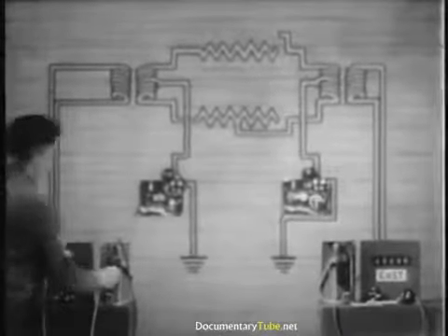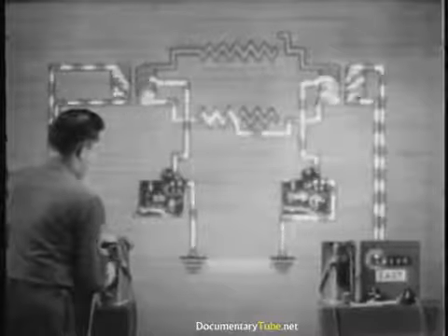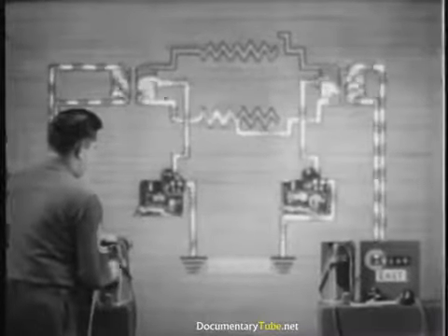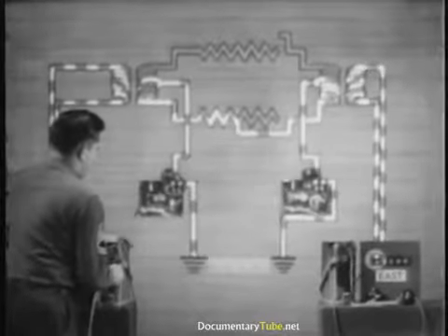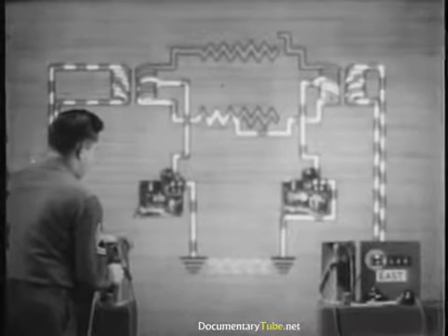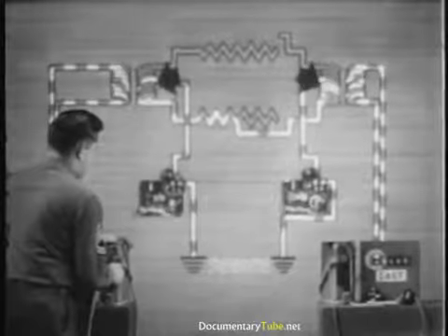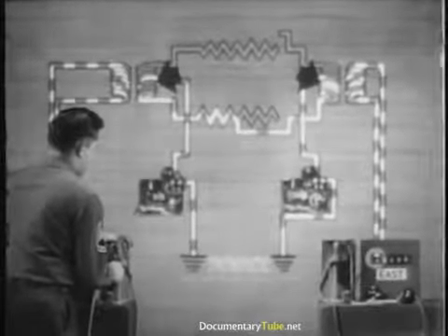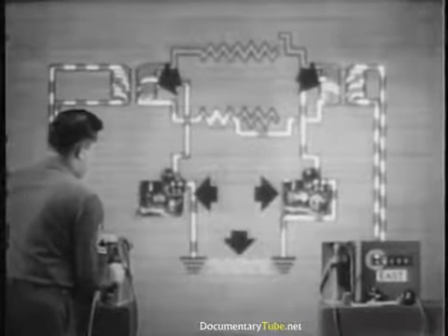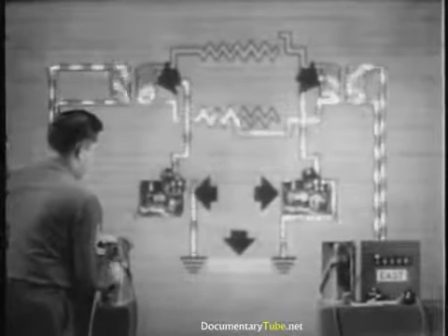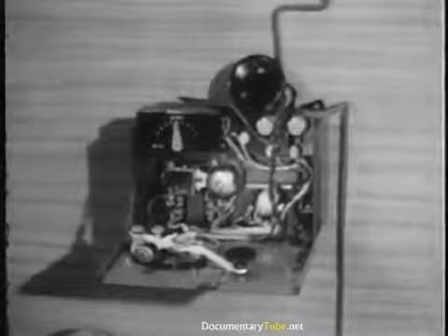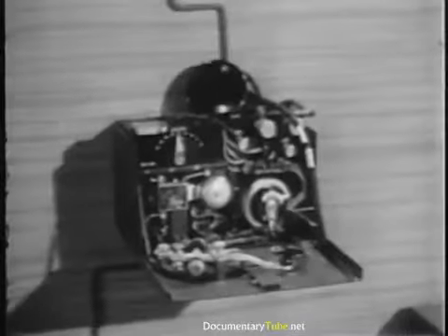Telephone signaling is usually still possible, even with the open line wire. The low-frequency ringing current uses the available half winding of each repeating coil, the telegraph sets, and the earth for its path. The ringing signal gets through, and this time it is strong enough to make the telegraph relays chatter and will cause audible interference in both telegraph sets.